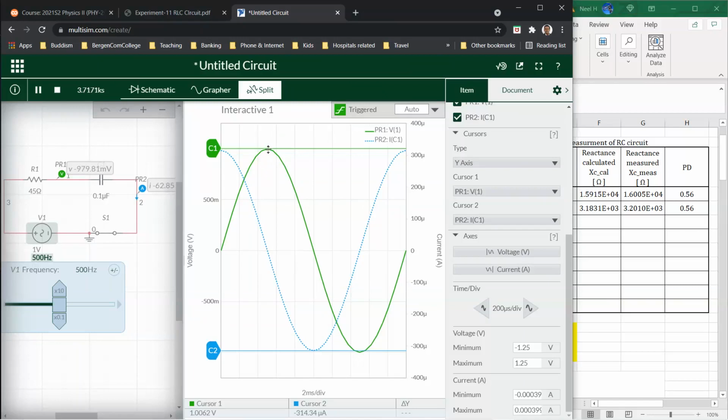Zero frequency technically looks like DC voltage. So the capacitor has a voltage, but the voltage does not change its polarity. So it's like the DC voltage. If you have a DC voltage, the capacitor will charge and then the current will be fully blocked. So the current should become zero in that case. Okay, that's the idea.